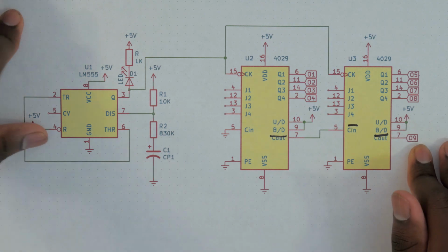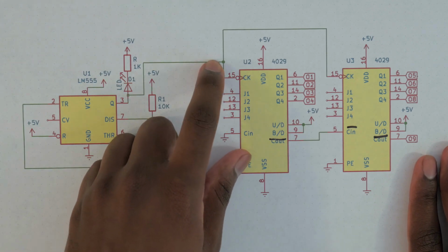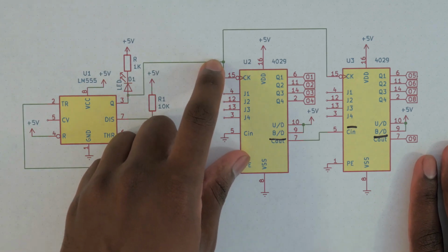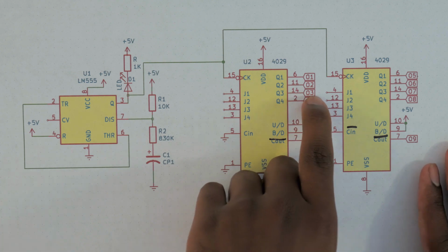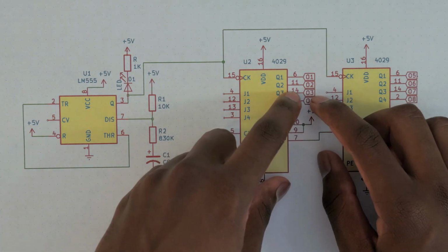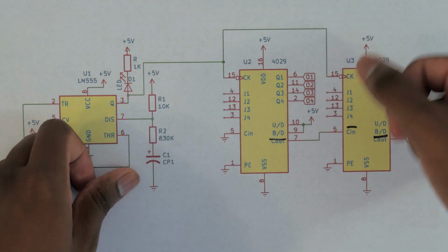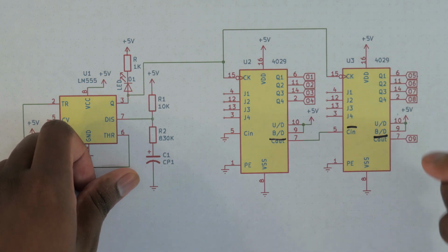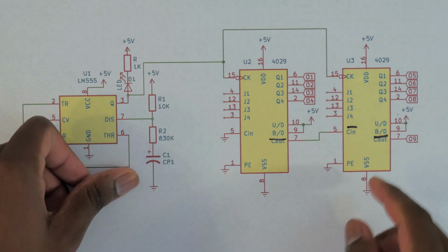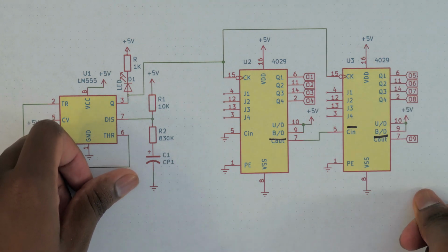Now the reason for this is because remember that the clock signal is 1 minute. So that means output 3 is our 4-minute signal. So that means we're going to need 8 bits past output 3. So output 3 is going to be our first, and then we need 7 more. So 1, 2, 3, 4, 5, 6, 7, and then we're going to need another 8th one, which means that we'd have to use 3 of these counters to ultimately get the 8th bit.